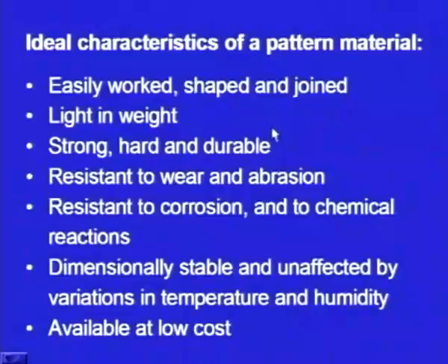And what are the ideal characteristics of a pattern material? One is, they should be easily worked. To give the shape, we should not find it so difficult. We should be in a position to give the required shape easily. And second characteristic is, it should be light in weight, and third, it should be strong, hard and durable.